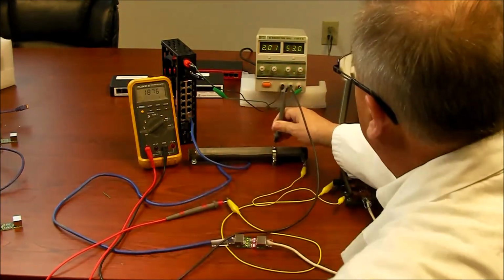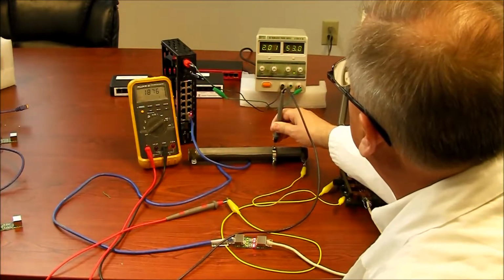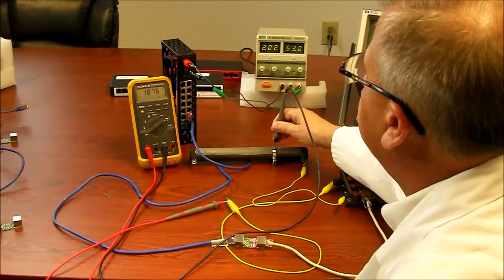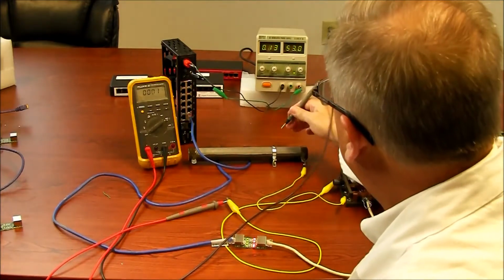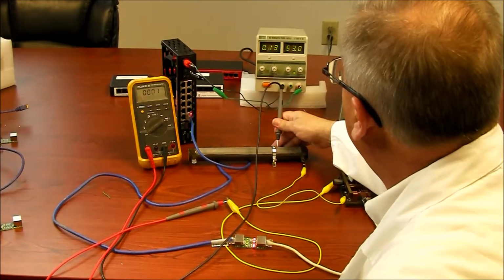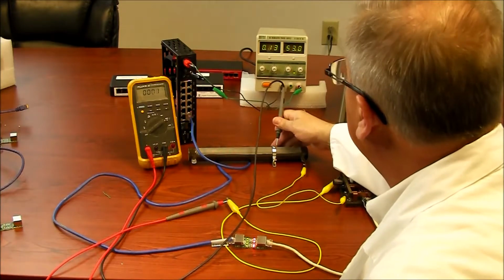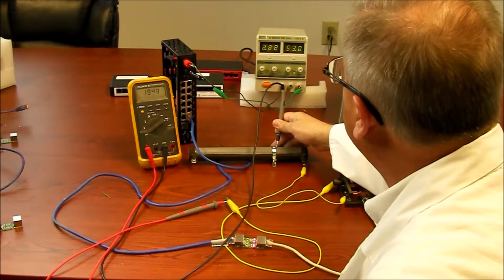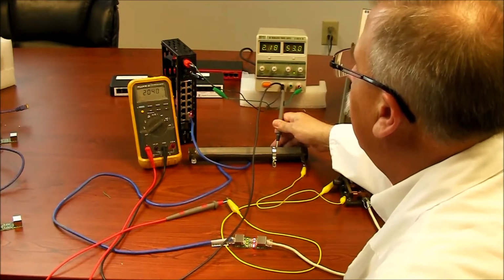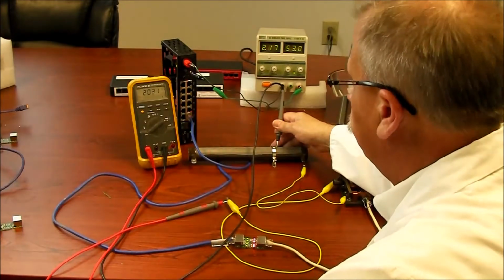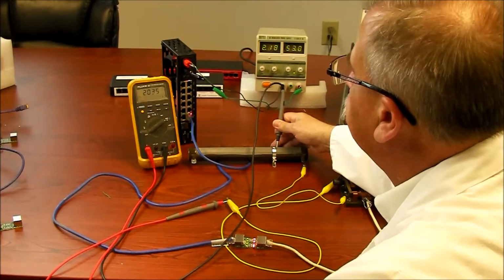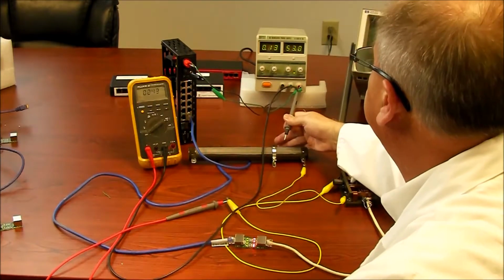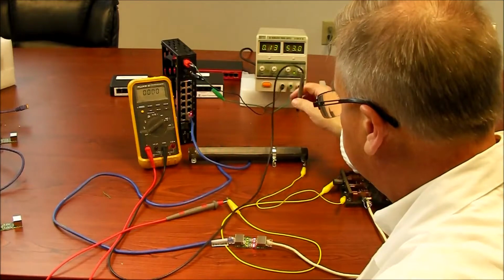You see, we're over 2 on the power supply, but we're not over 2 on the PoE. So let me tap just with my probe here a little lower resistance and see if we can get over. Wow, I wasn't surprised. I was not expecting to see fireworks there. Okay, there you have it, 2 amps. Switch is not blowing. Let this run all day long. The resistor's getting hot. I can feel the heat coming off of here.